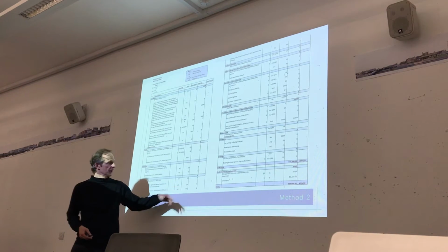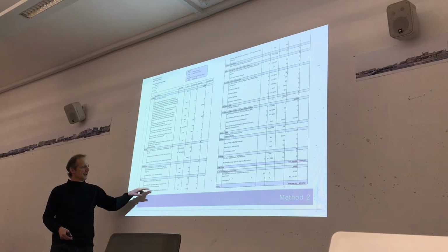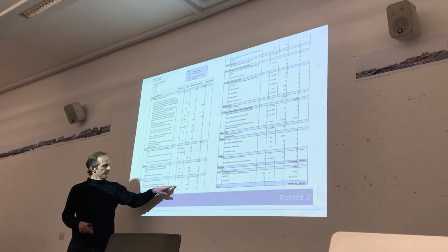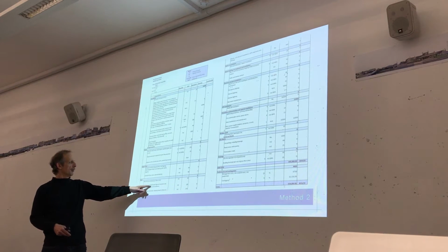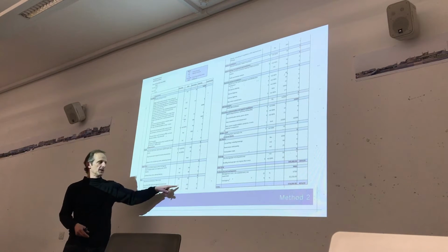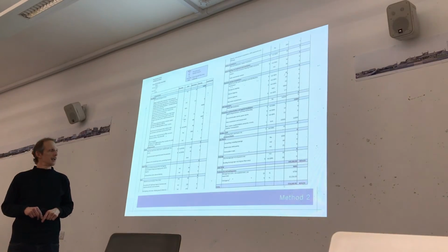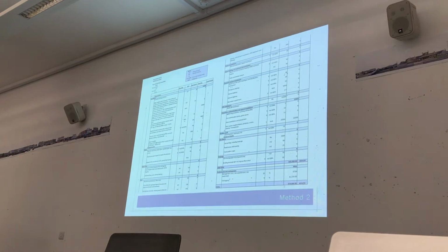So it's the roof. If that's the area of the roof, the area of the roof goes in here, that's the rate, that's how much it costs per square metre to do a plywood roof with a single ply membrane on it. It's £150 per square metre, and that square metre is actually the area of the roof. So where it says metres squared, now you're looking at the actual area of that element.